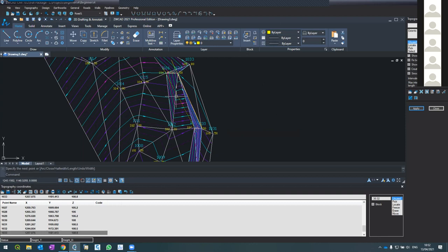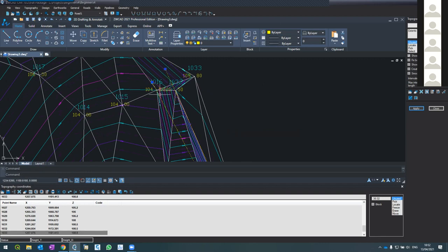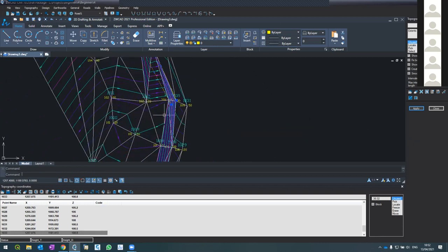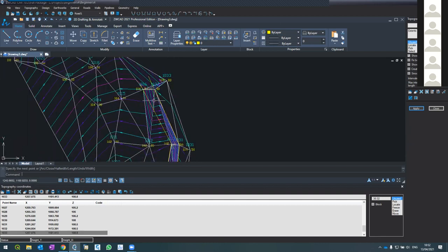This is where the cliff is, between these 2 points, these two lines, right? This is supposed to interpolate to this one, and this is supposed to interpolate to this one. I hope you got it. This one and this one define the cliff. In fact, it's the same like here, but here is okay, yeah. The cliff is from here to here, right? This is also the cliff, but here it's okay. Here somehow it's not okay. And why it's not okay? Look what happened to the triangles.